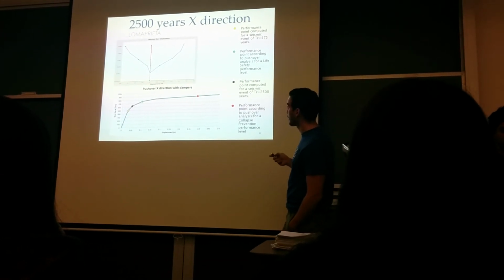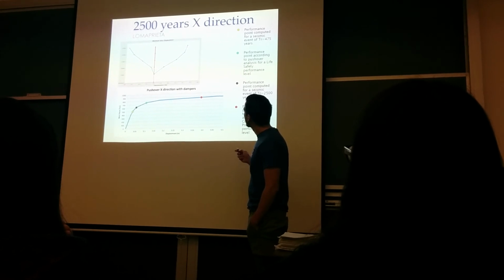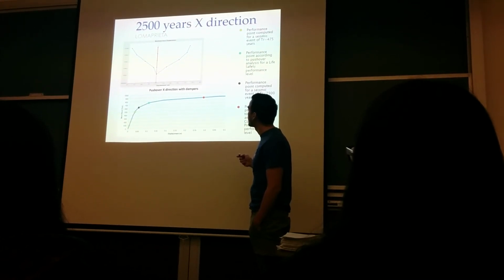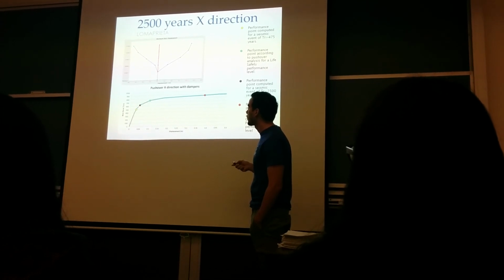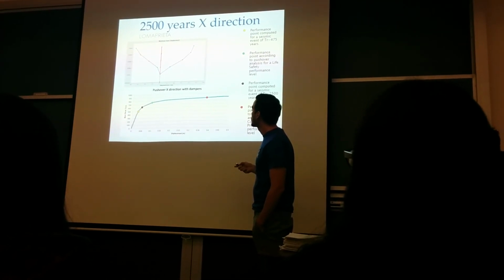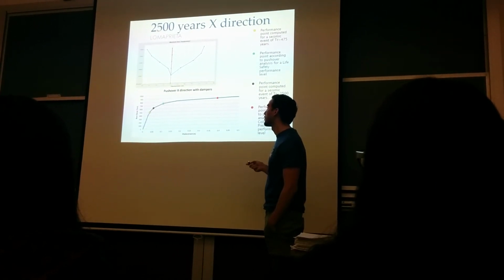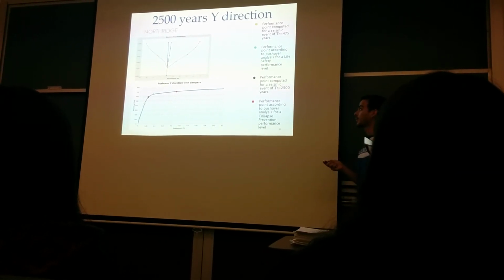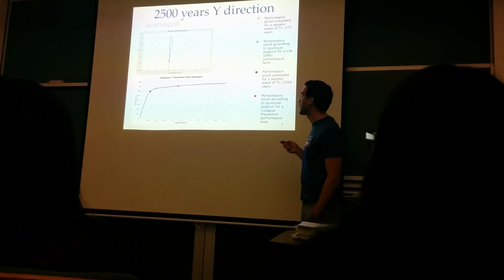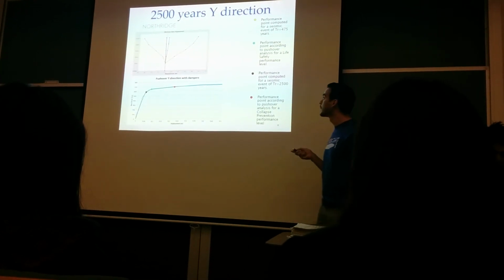Here we have, for example, the Normal period earthquake. You can say that 45 millimeters will be the maximum displacement. And if we go to the curve here, you can see that it will be here. According to the pushover analysis, this point lies behind the life safety and the collapse prevention points, so it will have a good behavior in this earthquake. The same with the Northridge. It's the same analogy. It will lie around here, behind these 2 points.